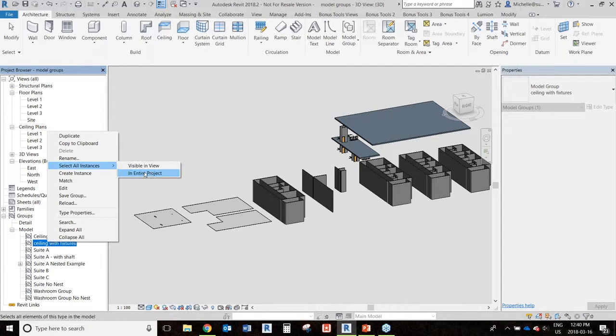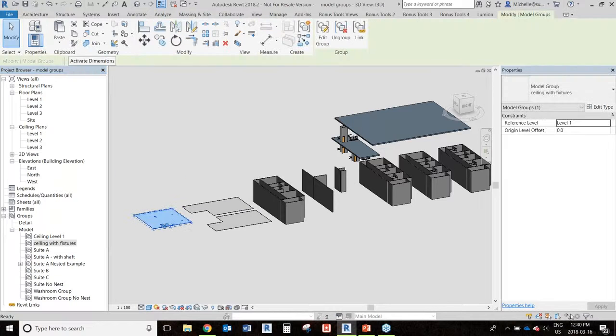The other thing that I always like to check for is if you select instances and you only see one of them. Again, another red flag to show that, you know, people are using a lot of groups where they might not need to be, just to group things together that are single instances. So that can also be based on how you decide you want to handle your processes for groups. That can be a way to manage how single instances are getting used.